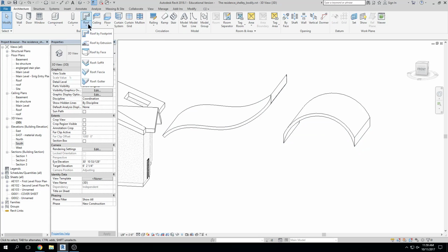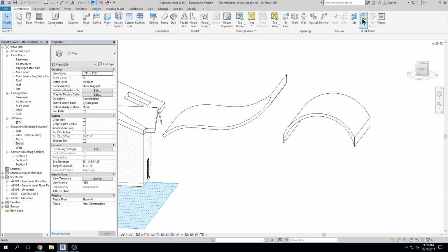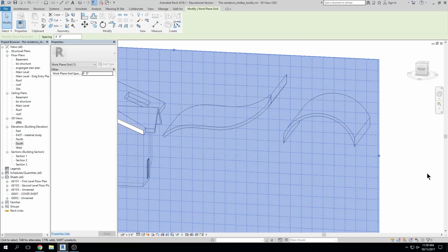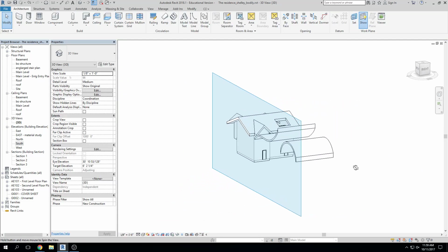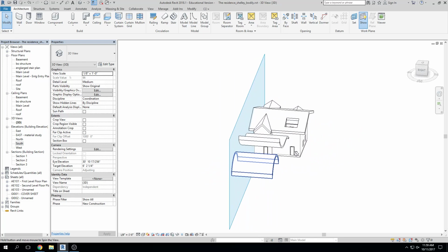So I liked how when I created it, it asked me for the plane and it established that plane. So I can see an outline of that work plane right there. Okay, show my work plane. There's that one. If I had the other one established, I could hit set. Let's choose extrusion roof. Then it sets that as my work plane, right? This work plane idea, until you've actually used it several times or worked in AutoCAD with it, might be a little bit foreign.